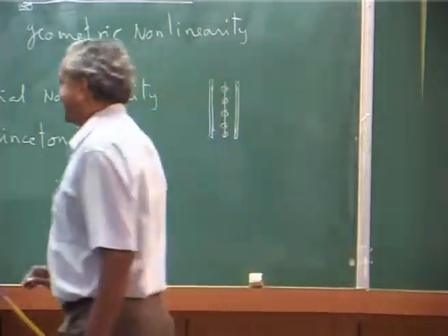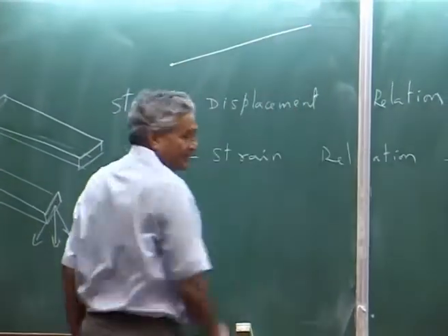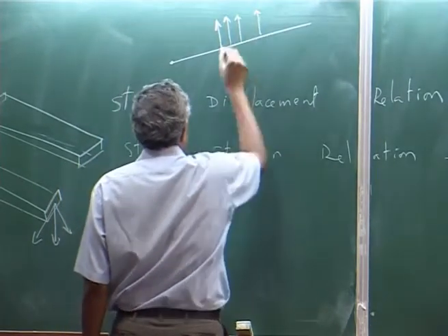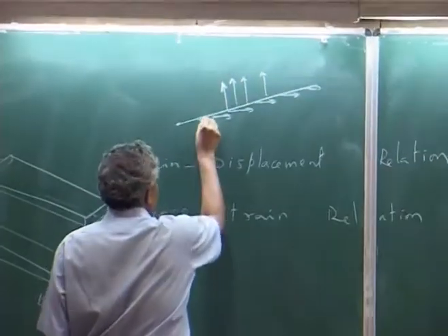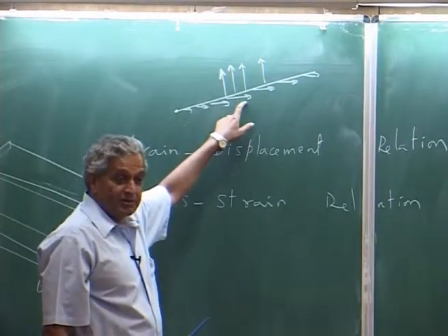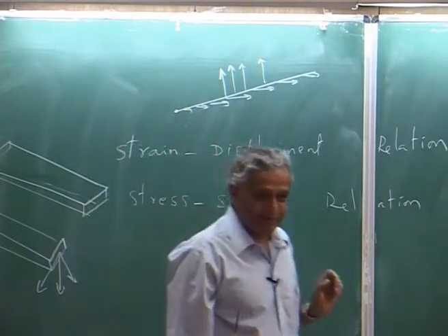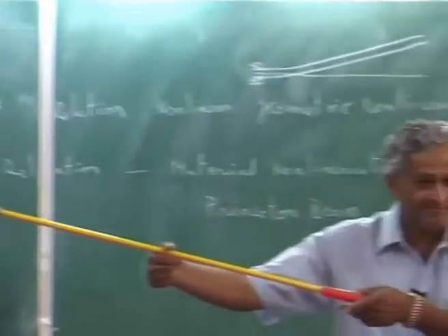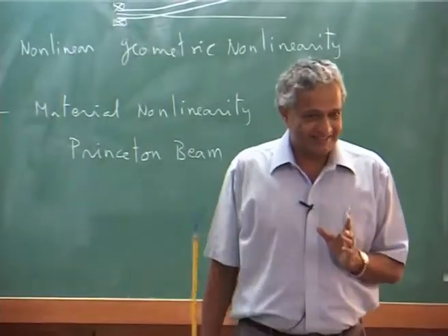It is not so here, that is what you have to know, because if you take this beam, your lift force is here, okay, and CF is here. Actually, the maximum bending moment is not at the root. Okay, you can have zero bending moment, and that is why you can have a hinge and you still have an equilibrium. You understand? So, you got it.